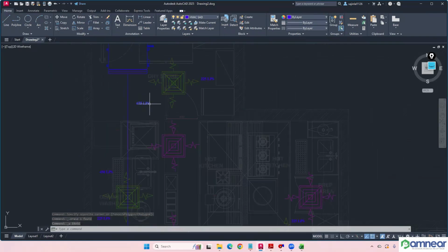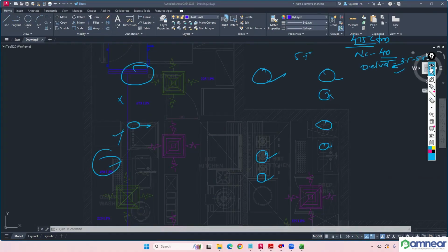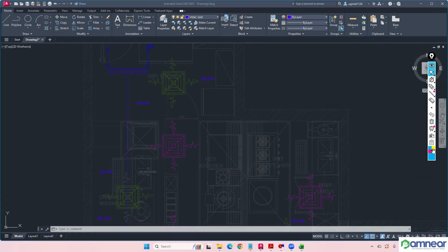Okay. Anyhow, 675. This for this project, from the bottom of slab to the false ceiling, correct. From finished floor level to the false ceiling, we are having 2.7 meter. Bottom of slab, it is 3.9 meter now. So clearly, 1.2 meter of false ceiling height is available.